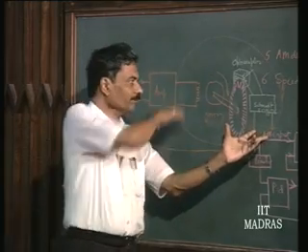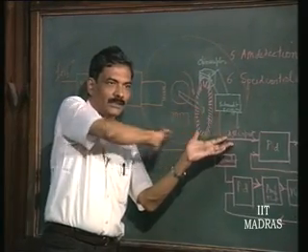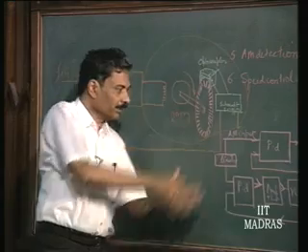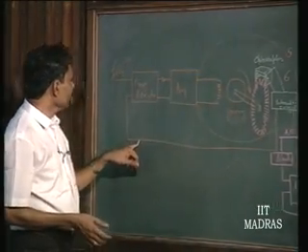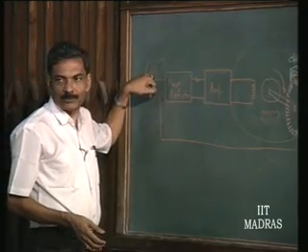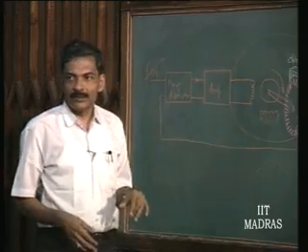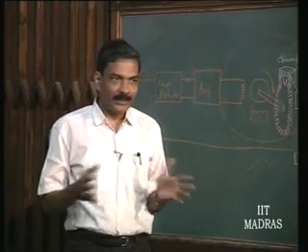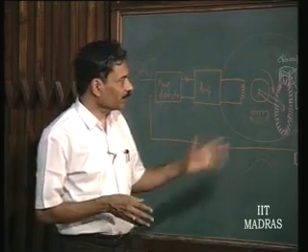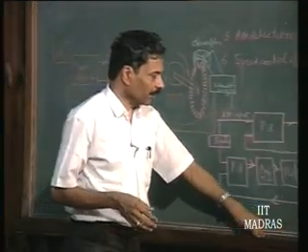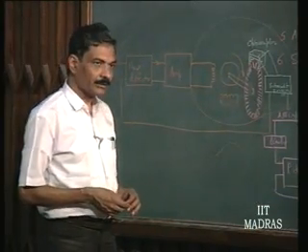So, once this becomes an integral part of the PLL system, this VCO becomes an integral part of the PLL system. What is going to happen is just as what happened in our ordinary PLL, this frequency will be exactly same as the input frequency. So, irrespective of the load on the motor, the frequency is going to remain constant. That means, speed is going to remain constant. Okay. This kind of speed control is nowadays universally applied, okay, in almost all precision speed control schemes.